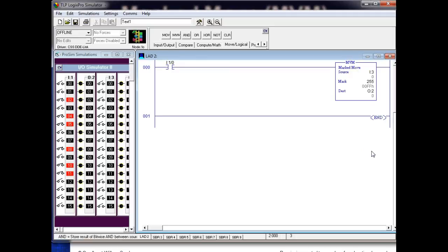So 00FF, what's it going to do? It's going to strip off the upper 8 bits because it's an AND mask. In an AND mask, if I've got a 0 in my mask, it doesn't make any difference what's coming in on my other operand. Those bits will be stripped off. I'm getting it from the other port, by the way, because I'm using the first one to load it. What addressing mode is this? Direct.